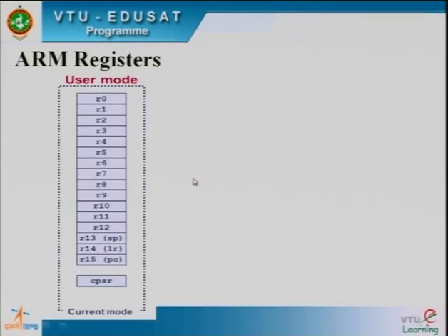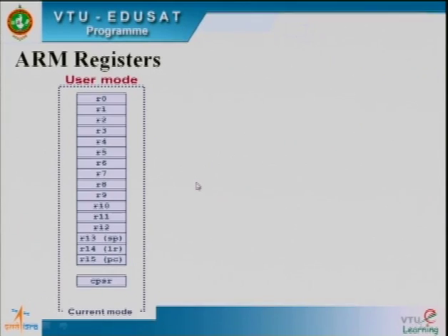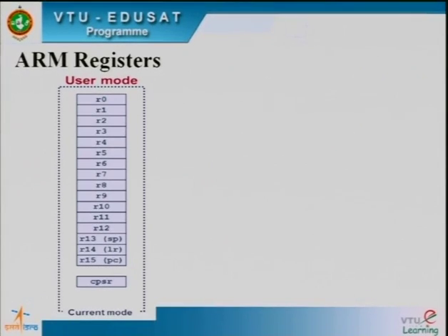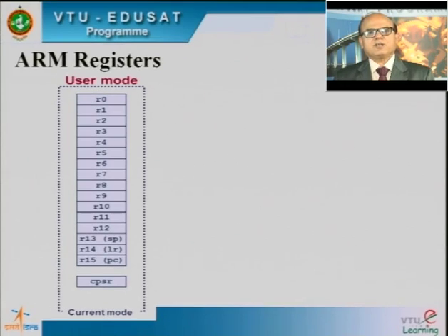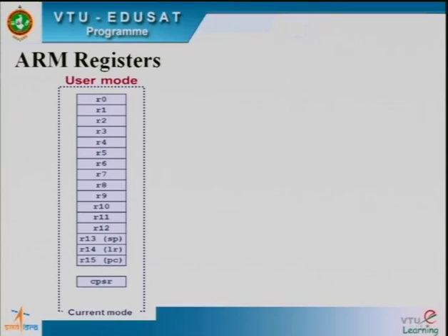Now coming to the next architectural feature, it is necessary to know the register file, because all ARM processors forward the operands to the ALU only from the registers, right. So no operand could directly enter the ALU fed from the memory, because ARM being a load store architecture, all the operands are to be stored in registers before they participate in the computation, right. So therefore it is necessary to know about the register file.